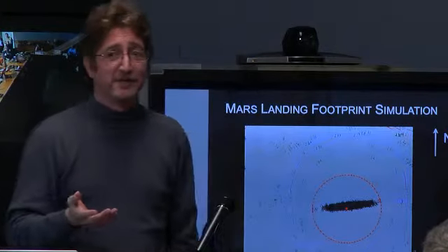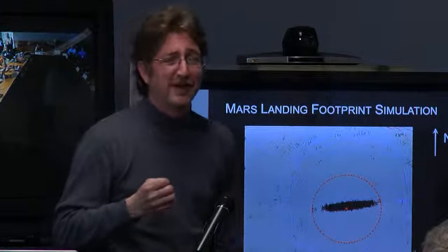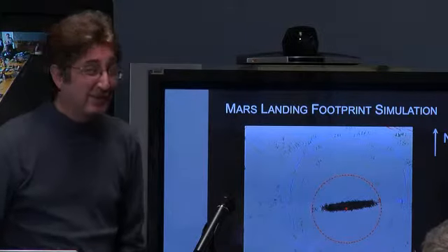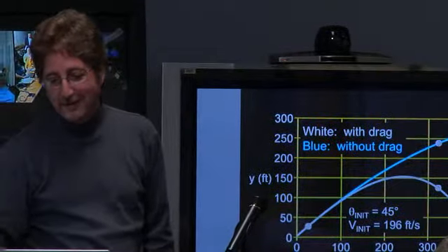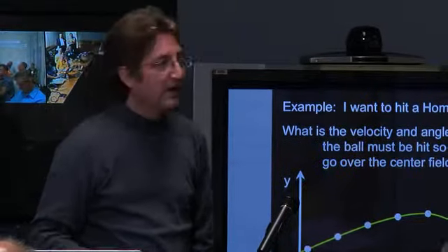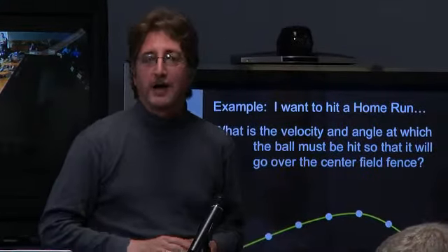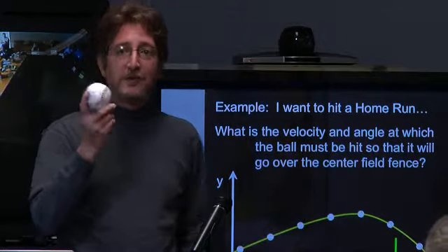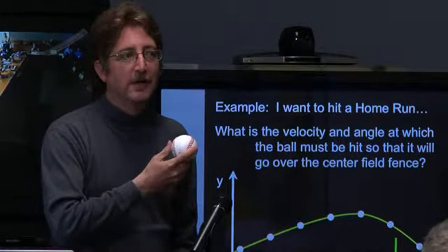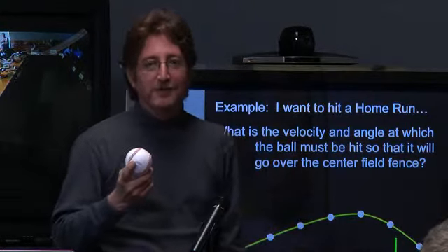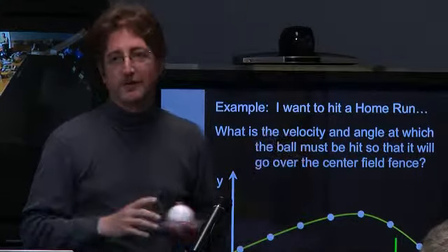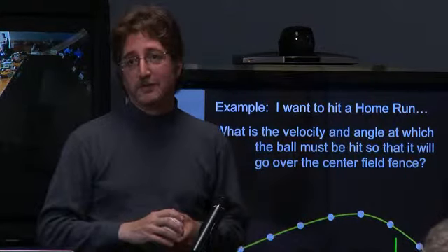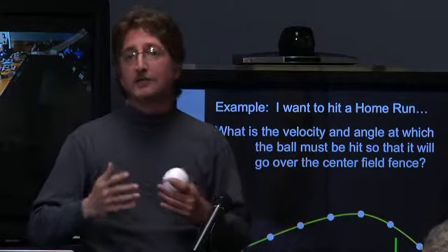Now, a really good question is: it's all great and good, but tell me again, why are you running 500,000 simulations a month? Can you do a few less simulations? Well, let me come back to that. First of all, there are a lot of things we're not absolutely certain of. If we go back to the baseball problem, what is the drag coefficient of this baseball? I used a number in there, but is it an exact number? No, it's not. It is within a range, and there's an uncertainty. So there are uncertainties on the inputs, and certainly also uncertainties on the atmosphere. That's number one.